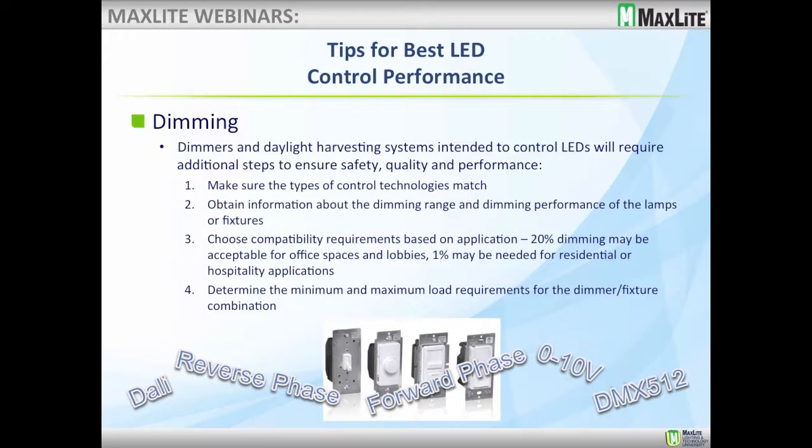So, the tips for best LED control performance. Number 1, make sure the types of control technologies match. Number 2, get information about the dimming range and the dimming performance of the lamps, especially paired with the kind of dimmer that you want. A lot of the controls people actually publish that information. As new lamps and fixtures come out, they test them, they publish the information,